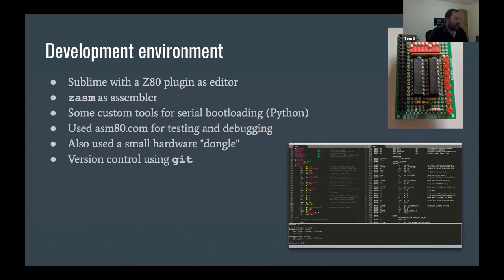And then the final little piece is a little hardware dongle, which plugs into the bus connector that was presented at the back of the CPU board. It's just got a latch and an address decoder on it. So you just configure an address via the dip switches, and then you just write, or just out, a byte to it, and it will display that value in binary on the LEDs. So that was good for using it as a progress indicator, or for debugging some value, like what value did I compute out of this function, or updating it to display a certain value.